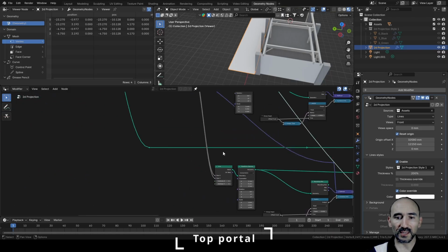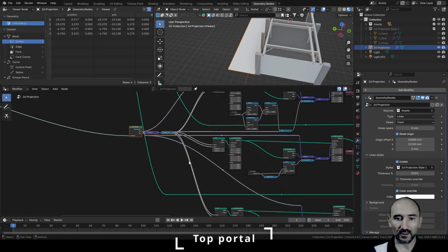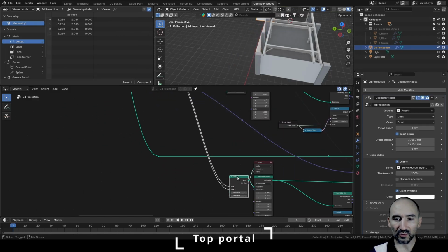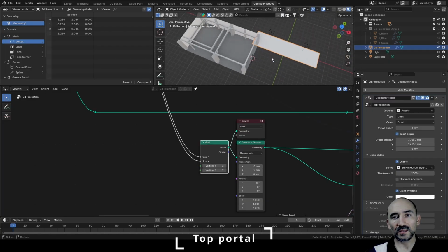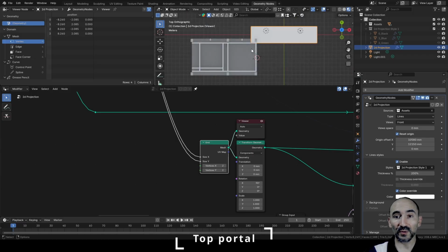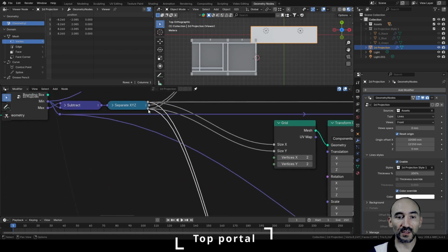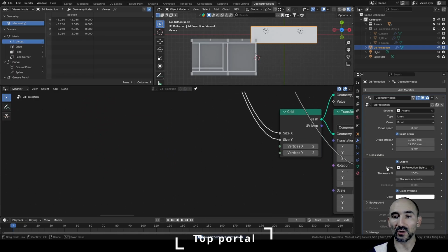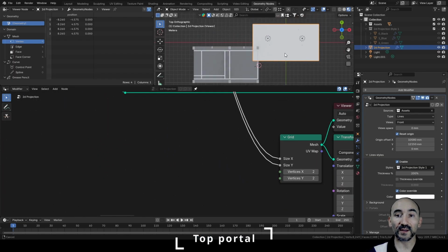And now we need to take the correct sizes, so I can move these a little bit, and if I press Ctrl Shift and click we can see this result, and we can see that the X size is correct, but from the top we need to have the Y size here in the Y socket. So we need to take not the Z part but the Y part of our collection of assets and link this value in the Y, and we have the correct rectangle.